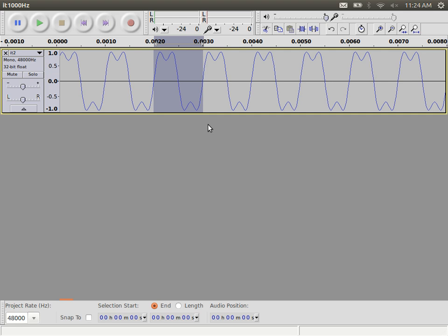What's the time frame? Well, we see from the software, it's from 0.002 up to 0.003 seconds, which is one millisecond. That's our period, the time that our signal cycle lasts. In 1 period, or in 1 millisecond, we can send 2 bits.